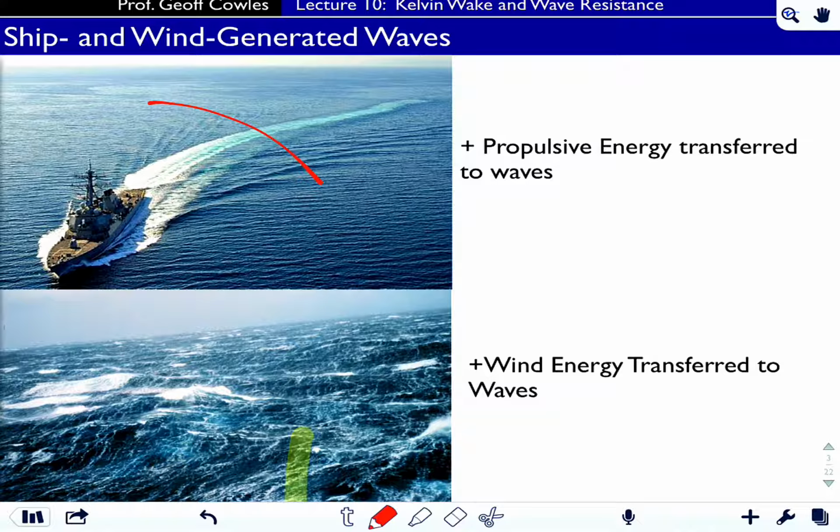Now, as we mentioned before, we divide it into a wave problem and a skin friction problem. The skin friction is easier to estimate. So essentially what we do in the wave tank is maintain the same Froude number, and I hope I have convinced you that in fact the wave train is connected with the Froude number.